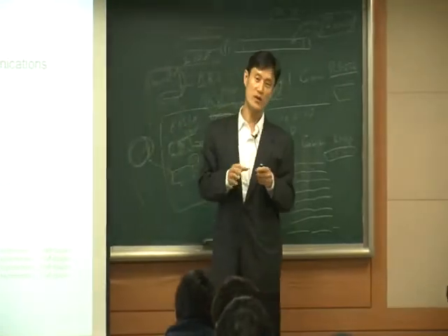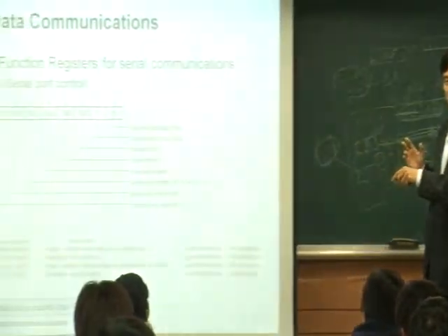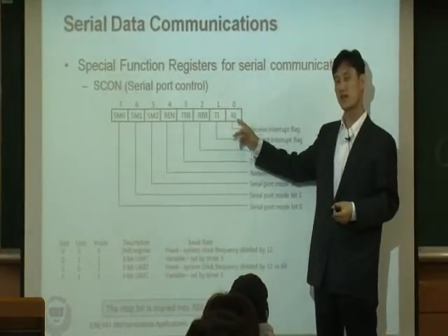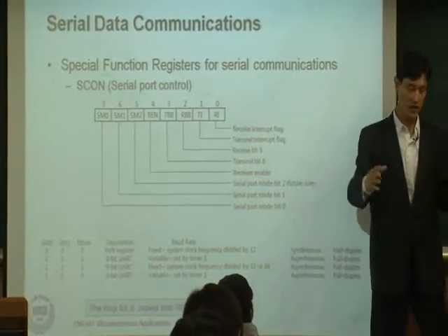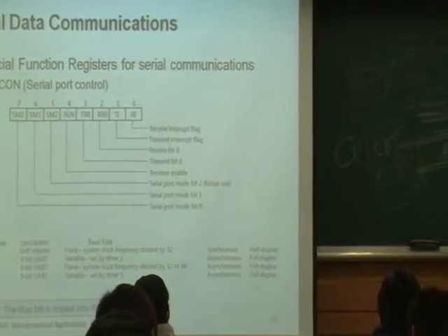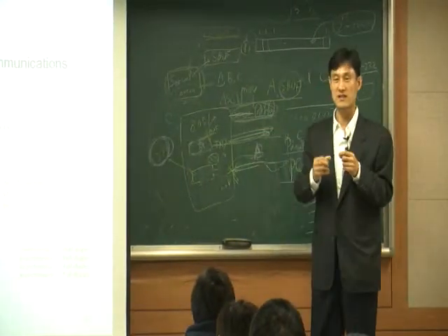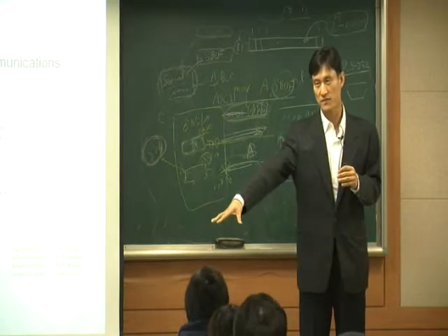In order to avoid such a case, that's why we need interrupt. So this interrupt, transmit interrupt and receive interrupt, is like a communication between the hardware and software. So what I do is something like this. Software, let's say I want to write ABC as fast as I can. Then I write the A value into SBUF.